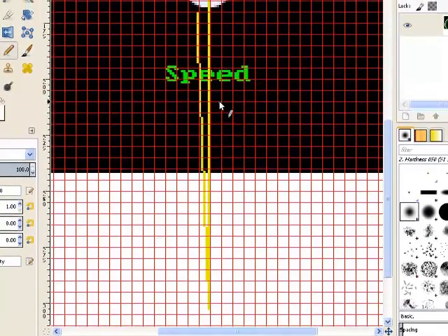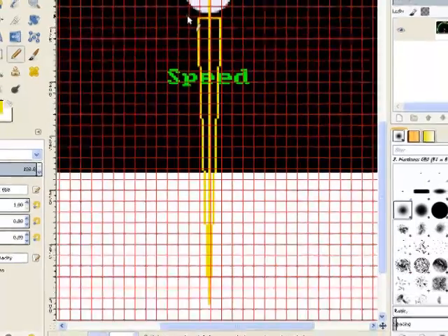And now we're going back up the other side. We're trying to be symmetrical, so we'll do Shift, click, and then Shift, click at the last point. And if you'd like, you can go to the first point to close the image. Shift and click. So that's the outline of your meter needle.